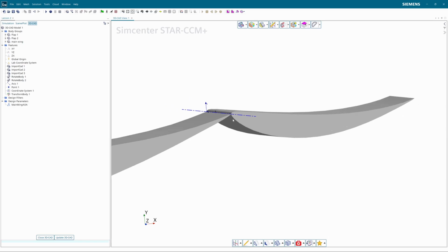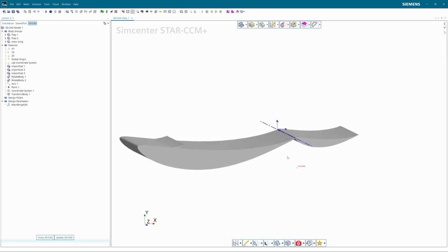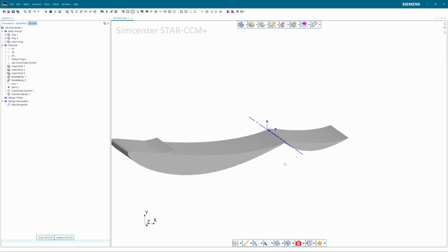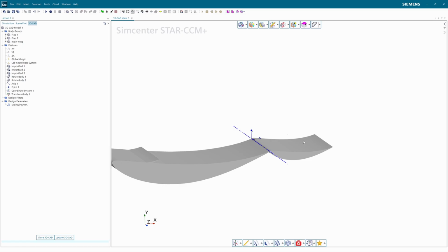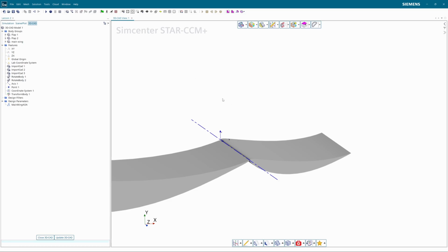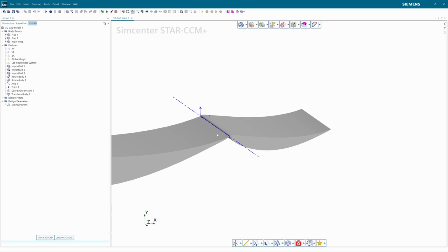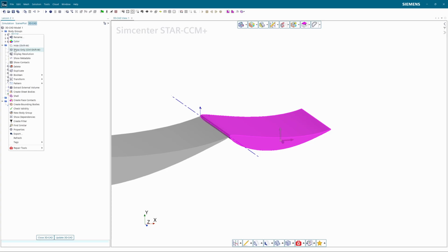Now, of course, it's sticking. This is not what we want when we're actually simulating, so we're still going to add 2 additional parameters. We're going to add 1 translate parameter and 1 angle of attack rotate parameter. It's important that you always do the angle of attack parameter first, because that way you can do it right after the transformation, and you can select this axis as its rotational axis, which will mean that its rotation is always consistent. If you do the translation first and then the rotate, it'll yield inconsistent results depending on the way you do it. So always be sure to rotate first before translating.